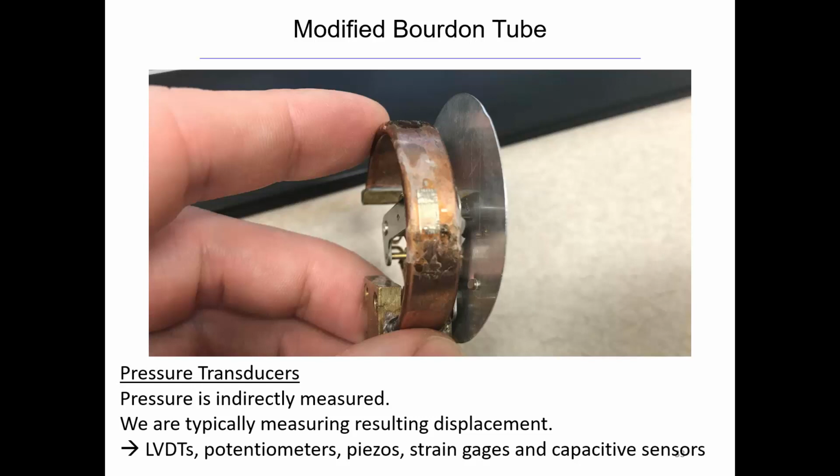You'd enter into your VI the actual pressure we were measuring, and you'd get a voltage reading out of that Wheatstone bridge corresponding to that pressure. By measuring a number of points, you can do a linear regression, find a line of best fit, which would be your sensitivity, and voila, you have a digital dynamic Bourdon tube.